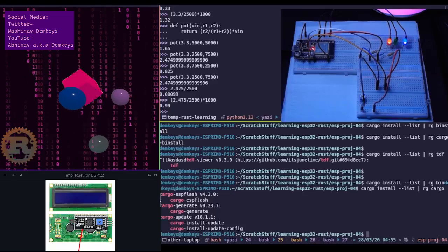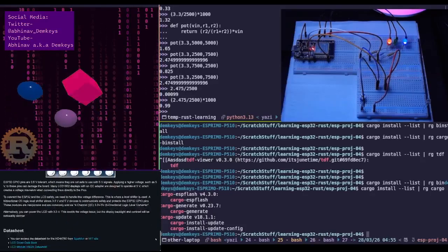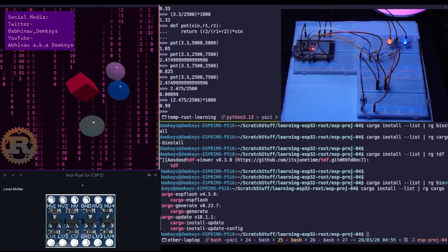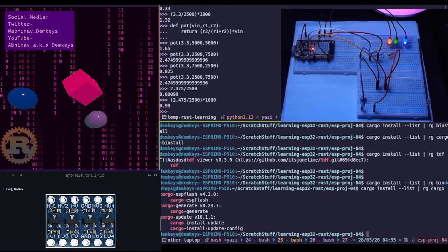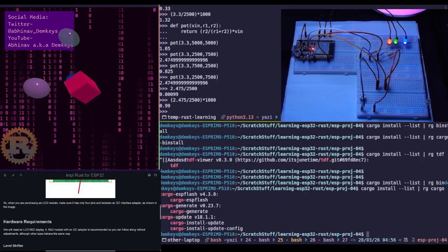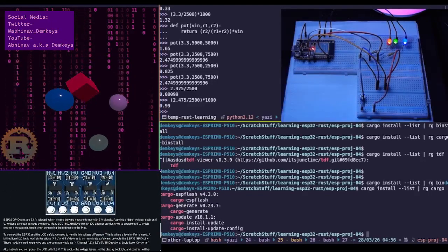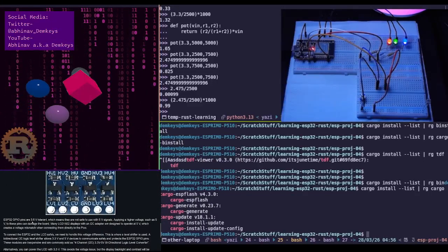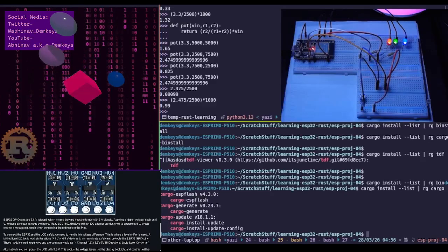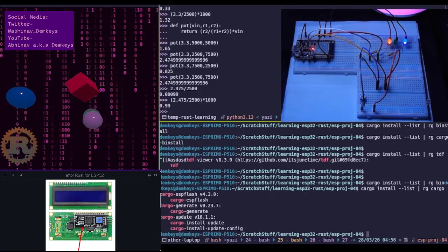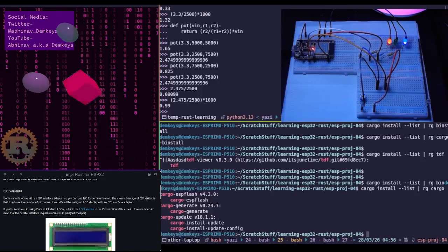But yeah, we can explore this as well. The good news is I also have a level shifter. It's mentioning here that we're probably going to be using a level shifter. GPIO pins are 3.6V tolerant, which means they are not safe. Oh, I didn't take that into account. Holy shit, I did not consider that.